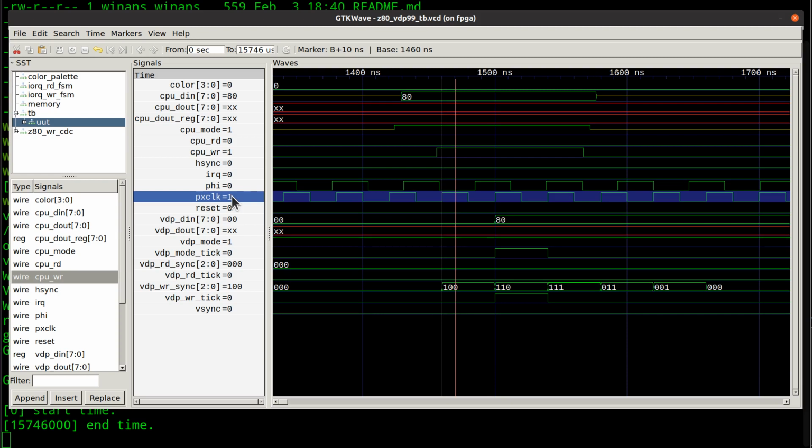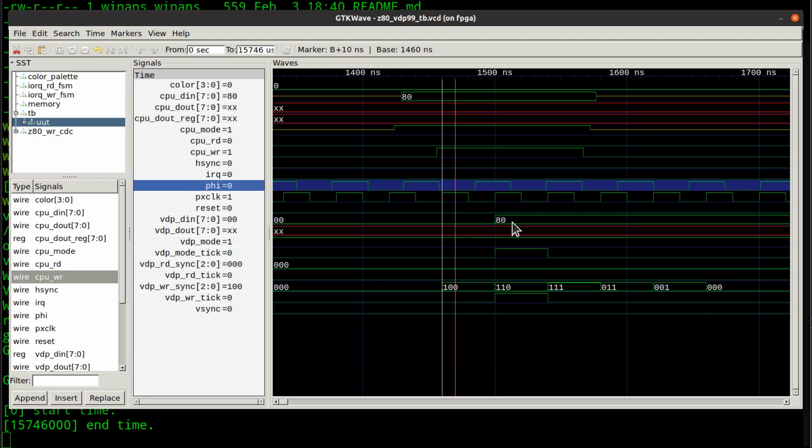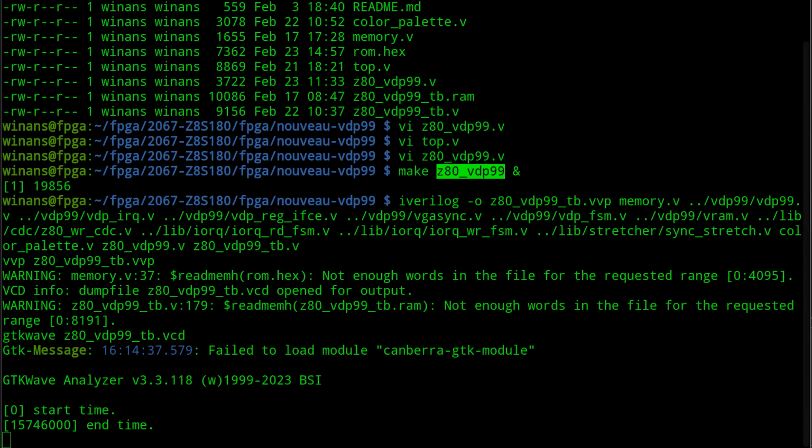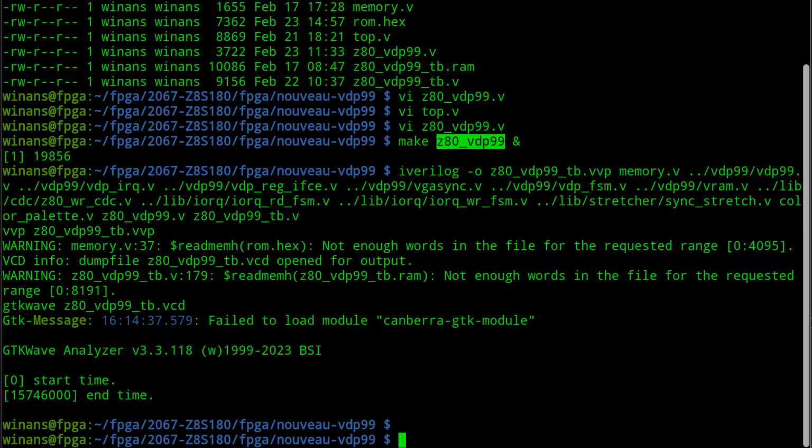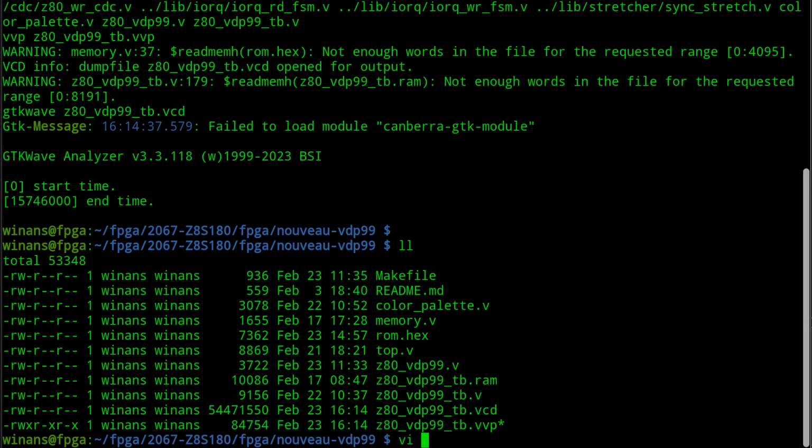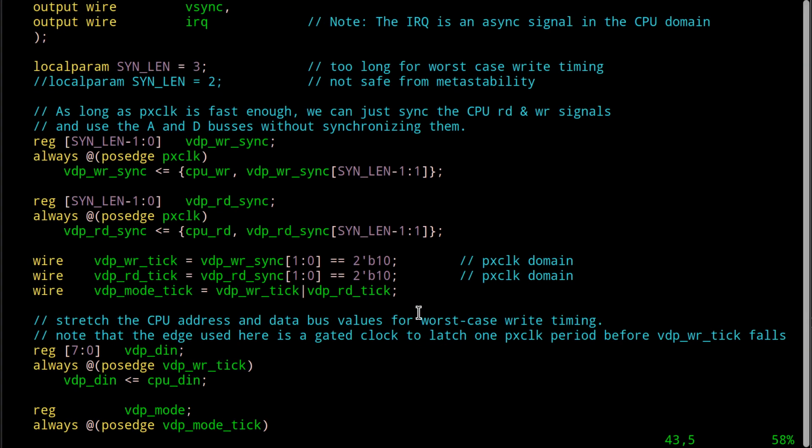The slowest it can ever go is going to be 25 megahertz. Okay, done. It'll always be faster than phi, and if that's the case, there will always be at least 2 periods, if not 2.5 periods of phi clock times in here for this signal to be recognized and shift up and so on and all that other fun stuff, okay? So I decided I'm going to use a simple implementation using these shift registers the way we're looking at right there.